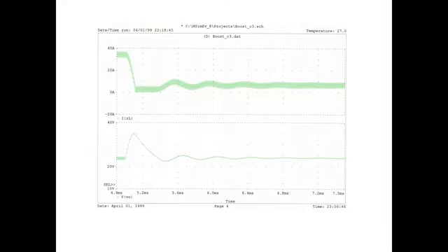But more to the point, what else goes on here? Here's what happens to the energy in the inductor, right? The inductor current, this is the inductor current here, it goes blam, it goes down to 0. Basically, the output voltage gets big, the converter says, oh my God, what can I do? The most I can do is turn my duty ratio to 0, and I turn my duty ratio to 0, and all that energy in the inductor ends up in the capacitor. And then it starts to switch again. But you notice here, things are clipped at 0. In this time period, this converter is actually in discontinuous conduction mode. Okay?